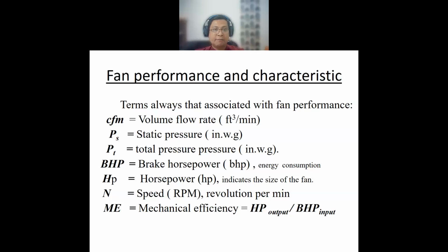The power will vary based on the size of the fan, and then speed. Speed is a common terminology when we talk about something related to rotating. And then mechanical efficiency, ME, we can determine by the formula HP divided by BHP.